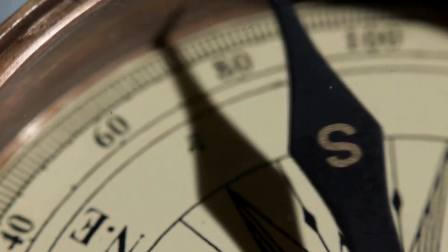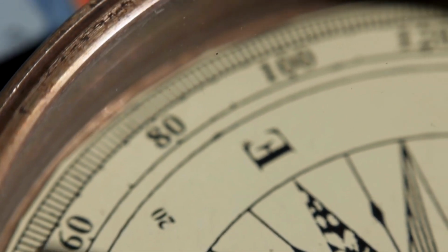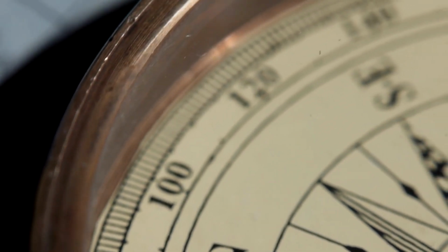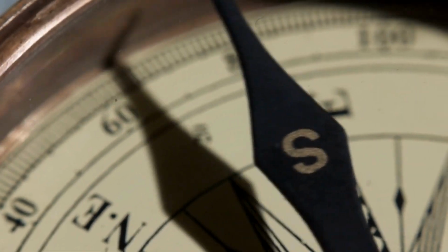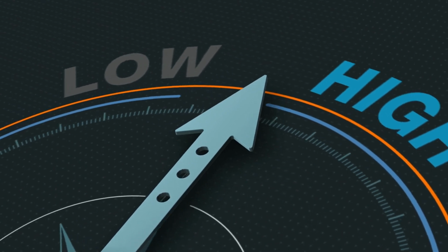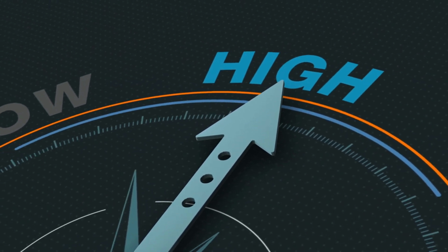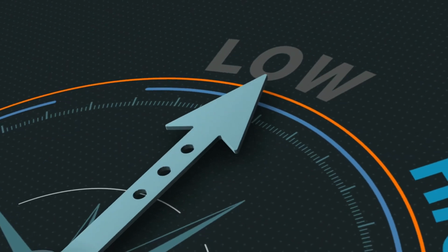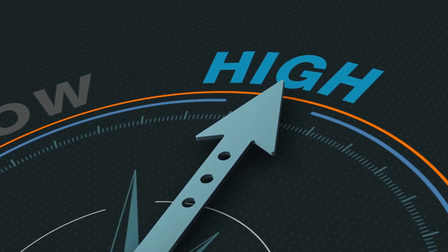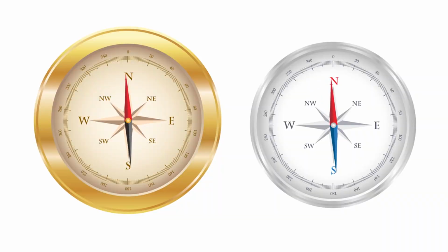The fluxgate must be kept as flat as possible by mounting it on gimbals or using a fluid suspension system. All the same errors are inevitable when the vessel is being tossed around by rough seas. Fluxgate compasses are also subject to deviation and variation and heeling error. However, it may be possible to apply variation electronically, and there may also be a facility to swing the vessel and apply deviation automatically.